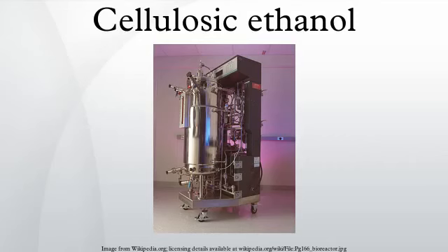Most pretreatment processes are not effective when applied to feedstocks with high lignin content, such as forest biomass. Organosolv and SPORL are the only two processes that can achieve over 90% cellulose conversion for forest biomass, especially those of softwood species. SPORL is the most energy-efficient and robust process for pretreatment of forest biomass with very low production of fermentation inhibitors. Organosolv pulping is particularly effective for hardwoods and offers easy recovery of a hydrophobic lignin product by dilution and precipitation.